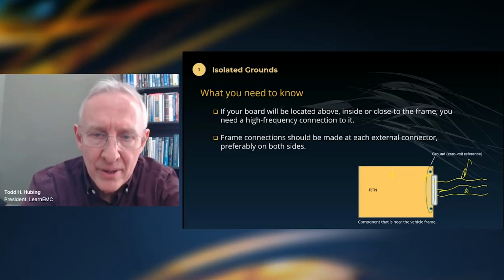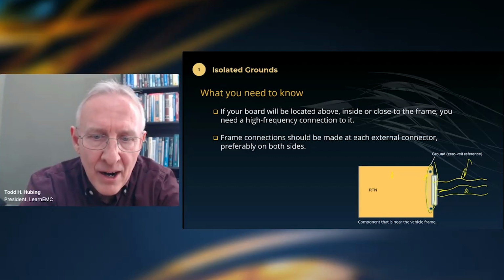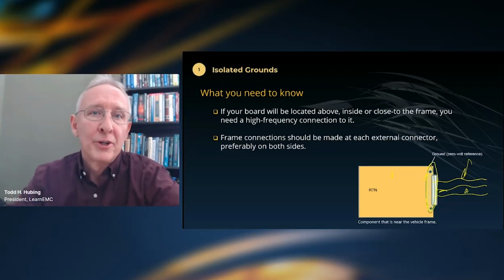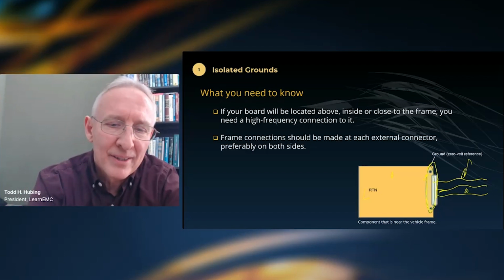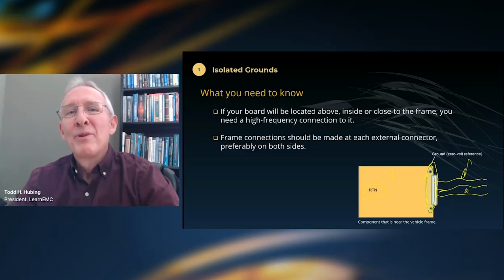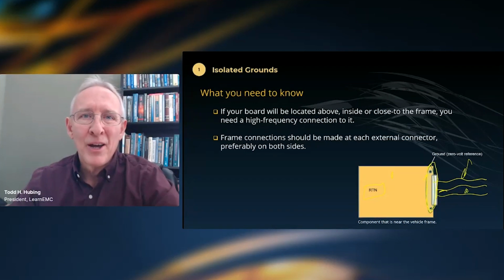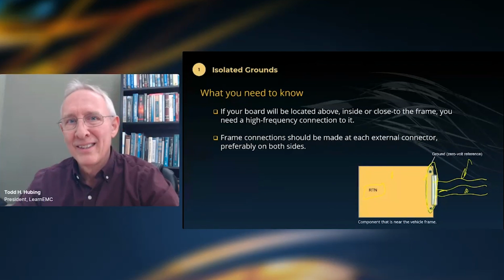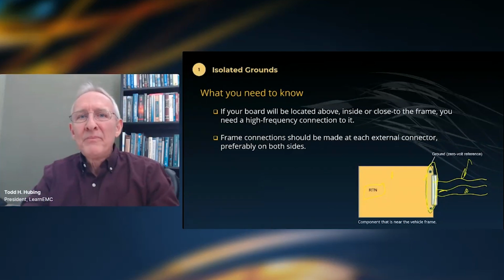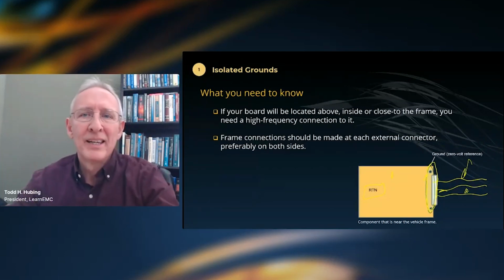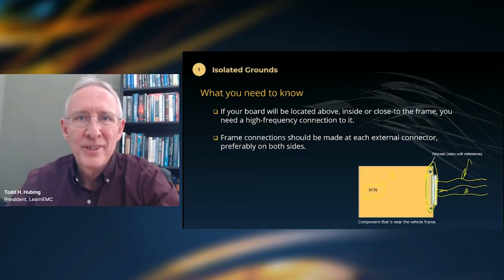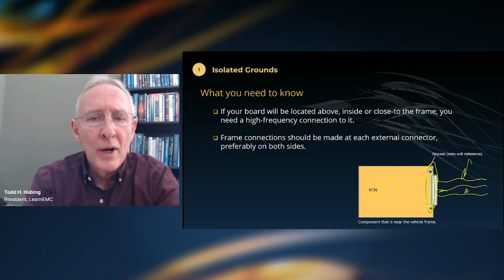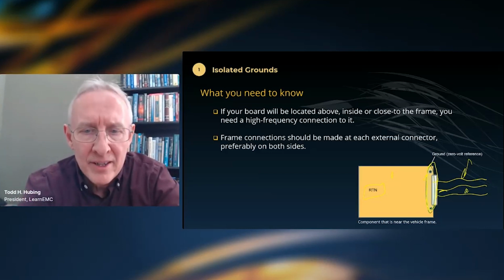So we need to make our connection to the ground. Where is our ground? Our ground is this area of our, say it's our digital return plane. And I've labeled it return because I prefer in board layouts to label the ground plane a return plane, just so people don't ever get confused and think that that's ground, and apply the rules of grounding to that plane. If you label it ground, of course, it doesn't change anything, but it allows for some confusion. So where is our 0-volt reference? It's this area of that plane right near the connector.